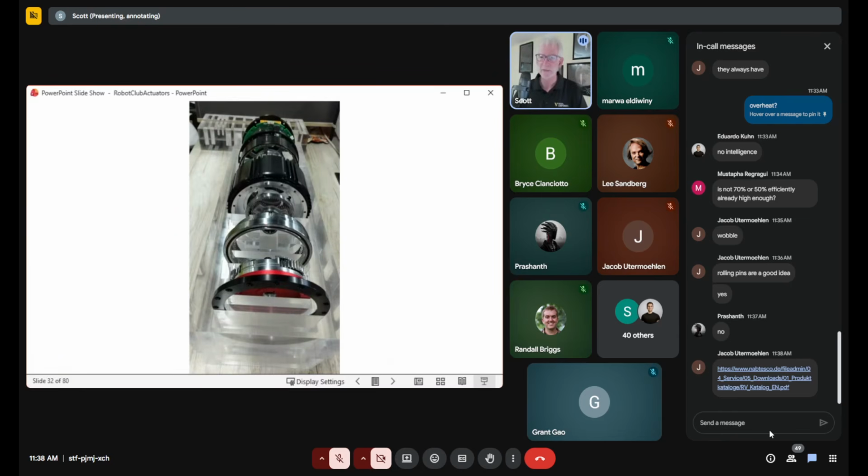All right, so again, we can kind of look how all these things get put together. In this particular case, what kind of reducer do you think that is? Planetary. Yes, it's a planetary, and it turns out it is a multi-stage. And the reason for the multi-stage is that they probably needed high torque, which means a higher gear ratio, and that means you're getting into, is it a QDD or not? Now, does anyone know is there a strict definition of what QDD is?